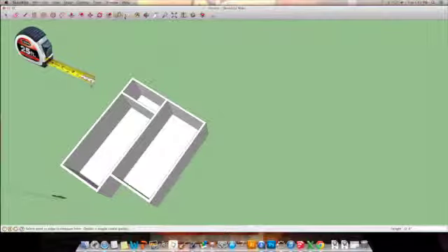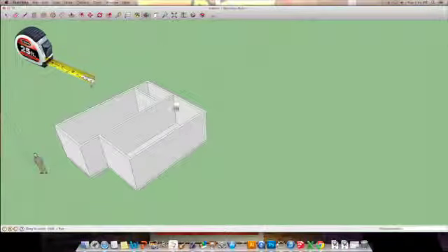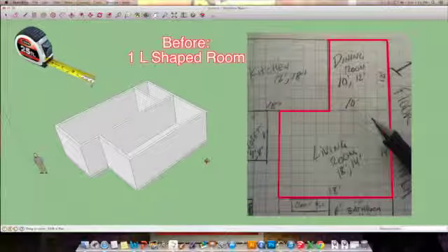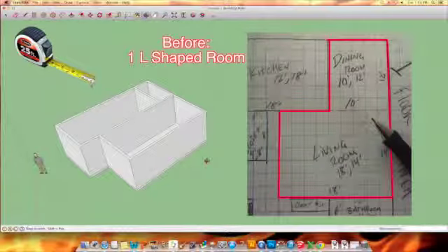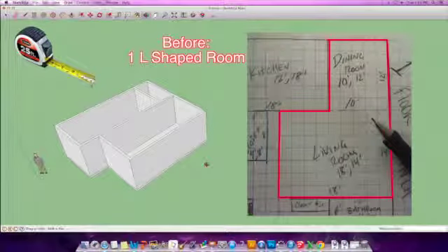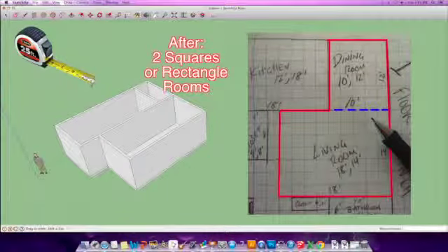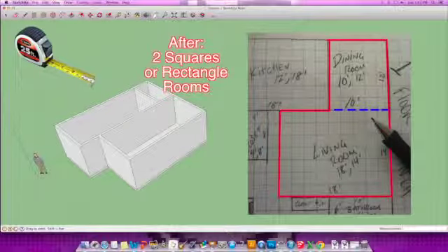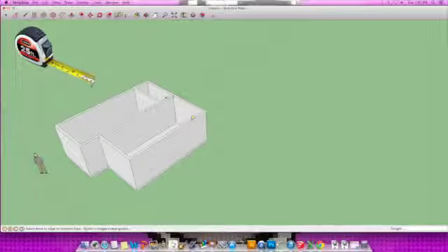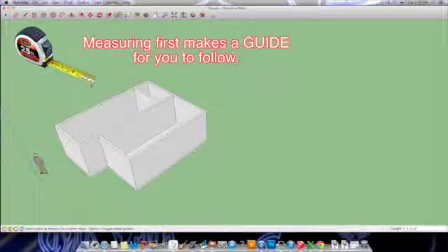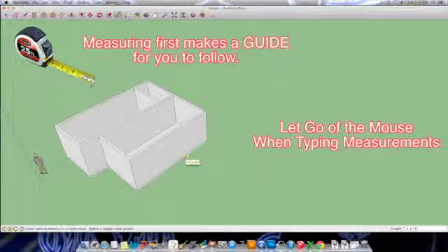All right. So what we're going to see in this next video is how to continue adding more spaces in different ways. I hopefully already explained in the previous video that when we look at our paperwork, our layouts, you should have squared or rectangled off everything just to make it easier to create the next space. In my case, my next room is only 12 feet, so I can't take this whole thing. I'm going to cut it again and measure 12 feet in this direction.